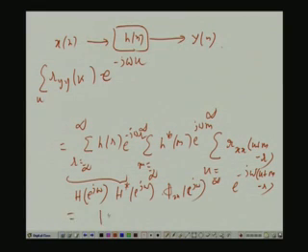So, again I get that filtering expression, mod h squared. Okay. This is a discrete time version of that previous equation. Okay. Again using this, you can show that phi_xx e to the power j omega also is a real function, but it is not only a real function, it is a non-negative function.